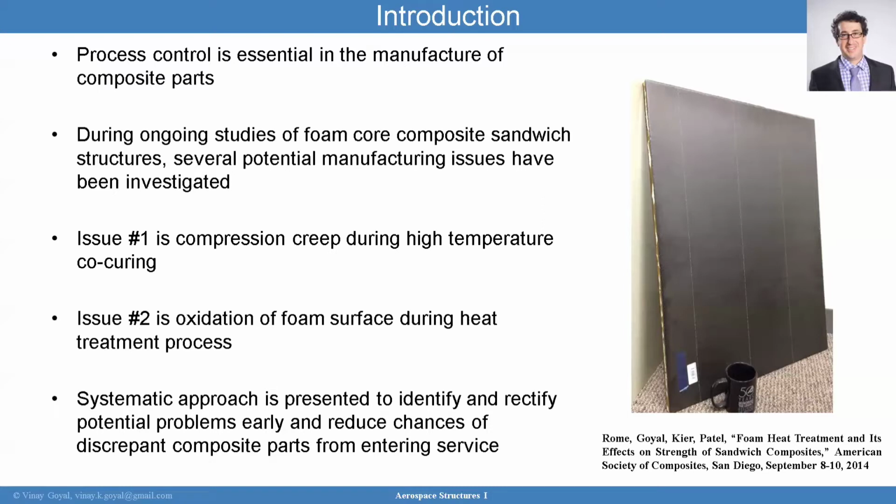Composites came along a long time ago, and it was like, wait, we're realizing that even if I have the same fiber and the same resin, I get different material properties each time, whether I make it at 2 different facilities or with 2 different crews. There's been a lot of work done to get more consistent performance, but you realize early on that you need to test what you're actually building with composites.